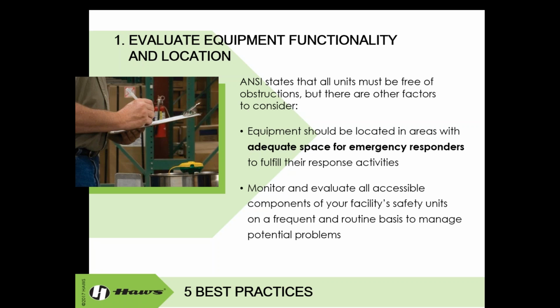For example, as Brian was touching on, typically in the event of an incident, there should be a responder guiding and walking along or running along with the victim to make sure that their clothing is removed and they access the appropriate piece of equipment. There should be no obstructions, but if there unfortunately is, that responder can assist in getting that out of the way and ensuring that the victim makes it to the piece of equipment. So it needs to be located in an area with enough space for the emergency responder to fulfill their activities. Again, this is not in the standard, but definitely important to take into consideration.